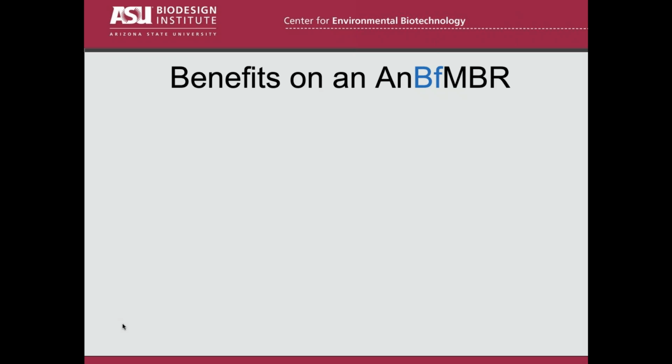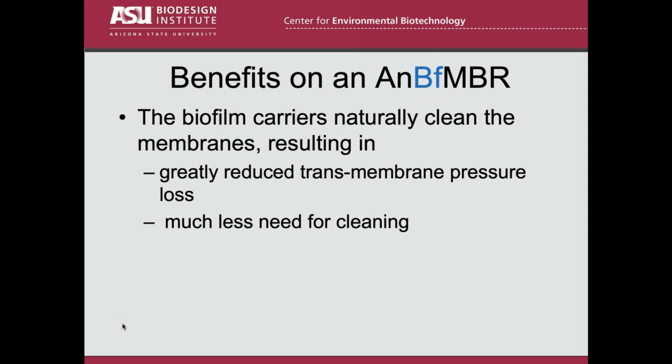So what are those big benefits of the anaerobic biofilm MBR? Okay, number one, if you configure it correctly, the biofilm carriers are going to be a natural cleaning mechanism of the membranes. They're going to be in there, bumping against the membranes, and you're going to get a gradual scouring of the biofilm off. So you're going to greatly reduce the transmembrane pressure loss. You're going to have to clean these membranes very infrequently, if at all. So this is a giant benefit, number one.